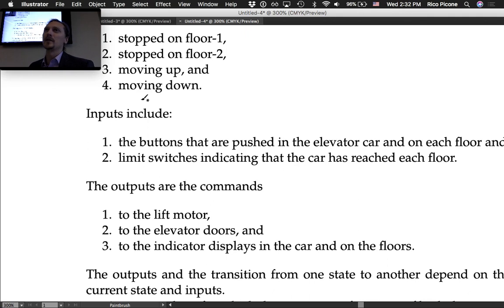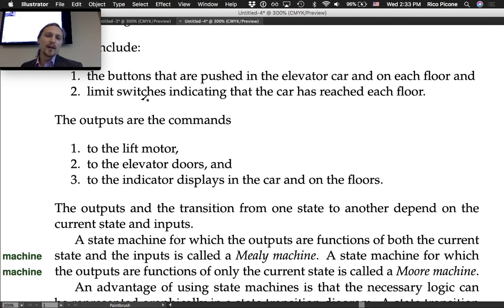So when they developed the control systems, they have like hardware level controls over this. Like if the door is open to the room, there's a hardware independent system that will not let power flow to accelerate the particles. So like, no matter what, if there's like some crazy bug in the software or whatever with the control system, at the hardware level, there's a switch that's going to disconnect and like it won't flow. And so they have these sorts of controls in there in very safety crucial applications. So something to keep in mind. But yeah, these are kind of cool, right? You could imagine yourself being in charge of designing this sort of a control system, right?